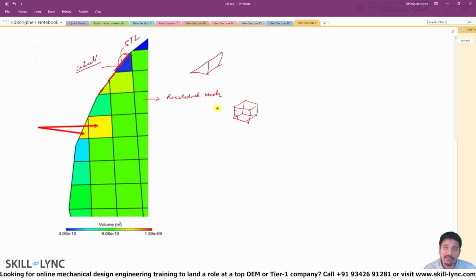Now, an interesting thing that occurs while setting up a CONVERGE simulation is called cell pairing. What does that mean? So for example, here you can see that you have one really small cut cell, correct? Now here is another example where the red arrows are. You have 2 cells. You can see that I'm coloring all the meshes by their volumes, correct? Now this cell definitely needs to have a much lower volume than this cell, correct? But why are both these cells colored yellow? And yellow means the volume is much higher than the green, right? So you can see that inside the volume is green, and in these 2 cells the volume is yellow, which means it's much higher. This is called cell pairing.